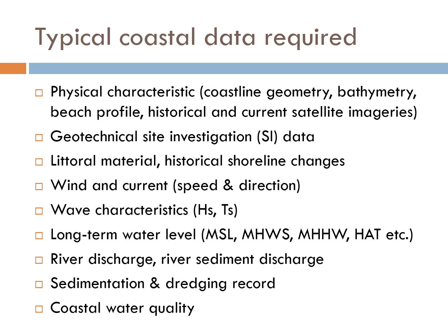For a coastal area where there is a river outlet, usually we will also need to find out regarding the river discharge and river sediment discharge, which will give us the sediment input from the upper catchment.